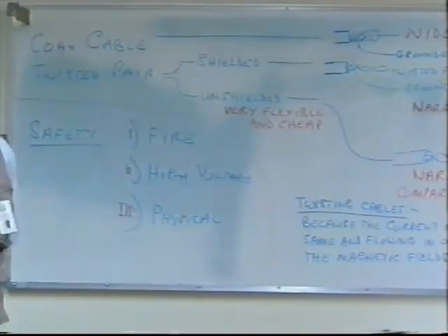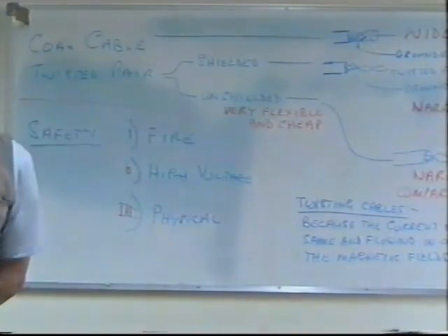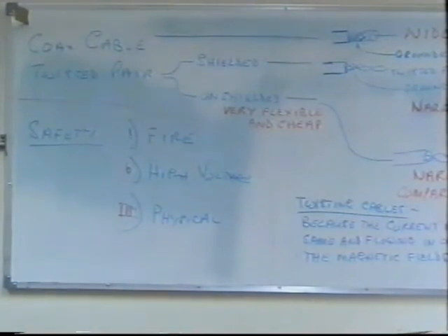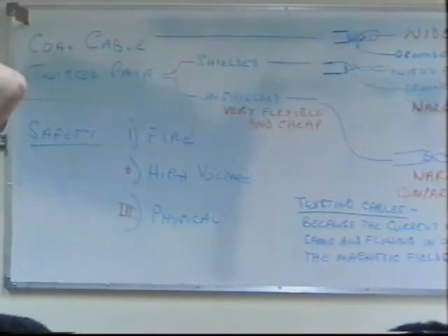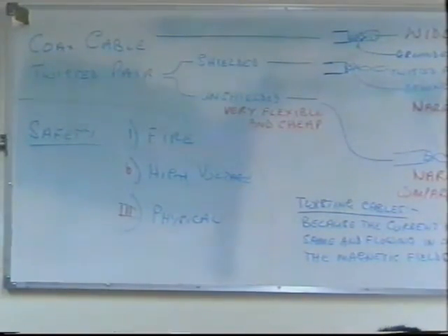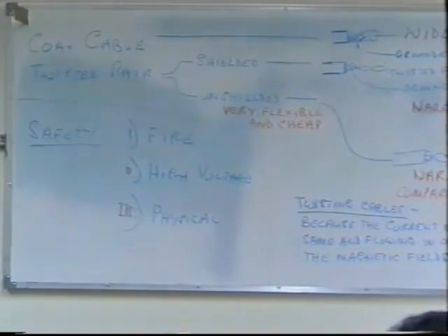Well, if you've got a fire and you know it's an electrical fire, even if you had a halon extinguisher somewhere, you're not going to stand there waiting for it to go off. You're going to pick up a small extinguisher if you can and put it out, aren't you? And the extinguisher you use would be coloured red, and it could contain powder, or it could contain carbon dioxide, depending on the class of extinguisher.